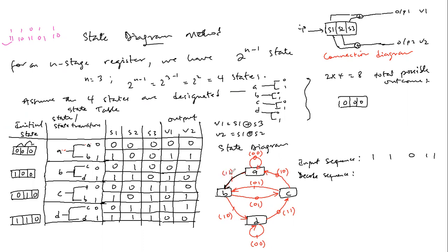And what we have here, the code word is 1, 1. And afterwards, from state B, we have to move again based on the fact that 1 is emitted. So we have to come this direction. Then we get to D, and another 1, 0 is emitted. Now from D, a 0 is emitted. So if a 0 is emitted, we go this part, and then that is 1, 1.